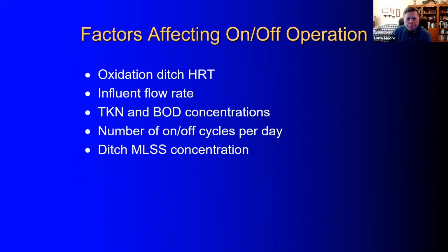So what are the factors we need to look at in on-off operation? The hydraulic detention time, the influent flow rate, the TKN and BOD loadings in the raw wastewater, how many on-off cycles we use per day, and what our ditch MLSS concentration is. But let me just say this. There are some conditions if you've got an oxidation ditch where you probably don't want to use on-off operation. I'm going to give you 3 conditions.